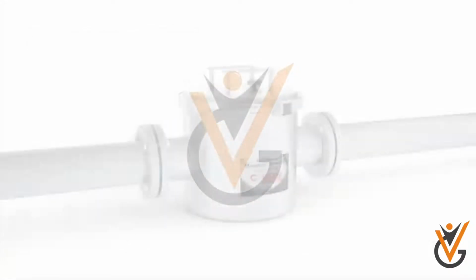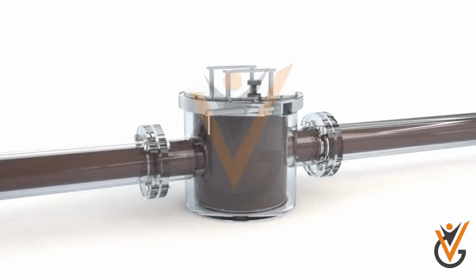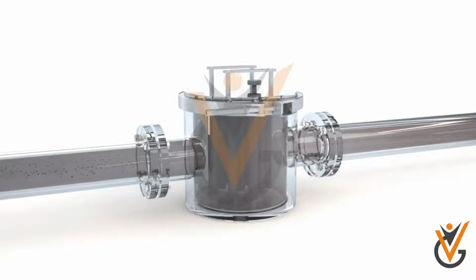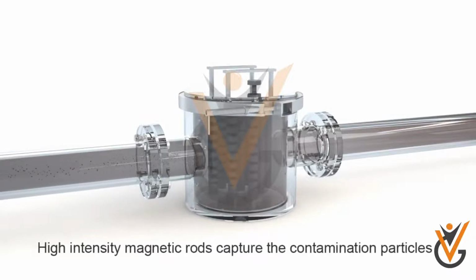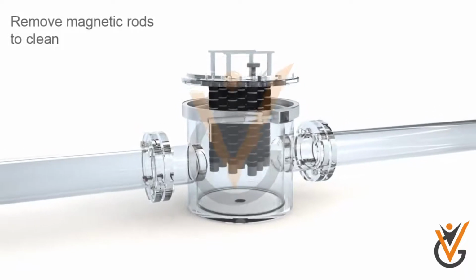Magnetic filter. Oil filtration in maritime industry is essential to achieving optimum performance, reliability and longevity. Lubricant cleanliness is highly important. Apart from the conventional filters, there are also magnetic filters, which are used to remove fine iron particles from the system. The arrangement of a magnetic filter is same as that of a fine filter, but with a magnetic element placed in the central tube.